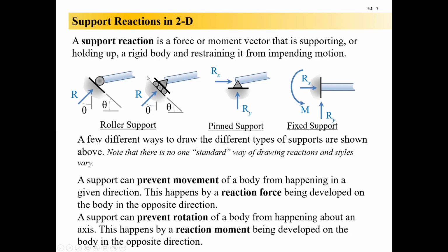But then this whole triangle is sitting on some skates, so it's like roller skates. It's sliding up and down this incline, and those are frictionless wheels. We always assume so. That only generates a force that is normal to the surface it's rolling on. So here, the reaction would look like that, pointing not straight up, but straight towards the roller from the ground. The ground is pushing up against the wheels with that force R.